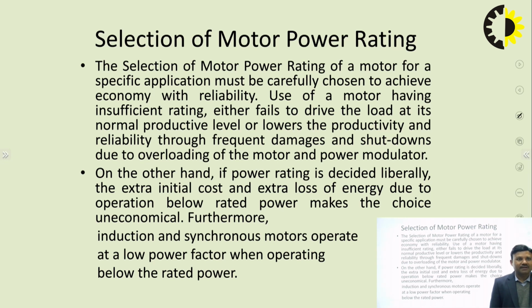The power rating of a motor for a specific application must be carefully chosen to achieve economy with reliability. Use of a motor having insufficient rating either fails to drive the load at its normal productive level, or lowers the productivity and reliability through frequent damages and shutdowns due to overloading of the motor and power modulator. On the other hand, if the power rating is decided liberally, the extra initial cost and extra loss of energy due to operation below rated power make the choice uneconomical.